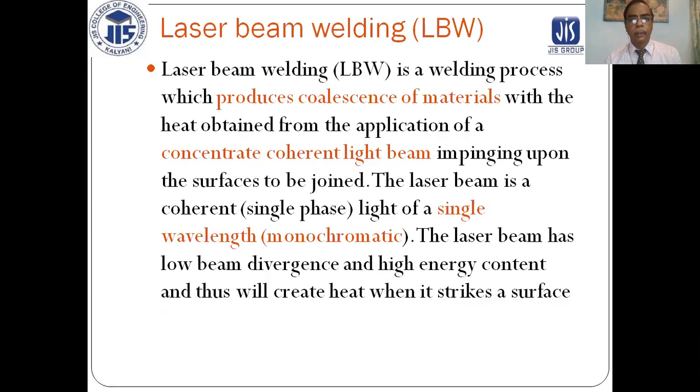Laser beam welding is a welding process which produces coalescence of material with the heat obtained from the application of a concentrated coherent light beam impinging upon the surface to be joined. The laser beam is a coherent, single phase light of a single wavelength, monochromatic. The laser beam has low beam divergence and high energy content, and thus will create heat when it strikes the surface.